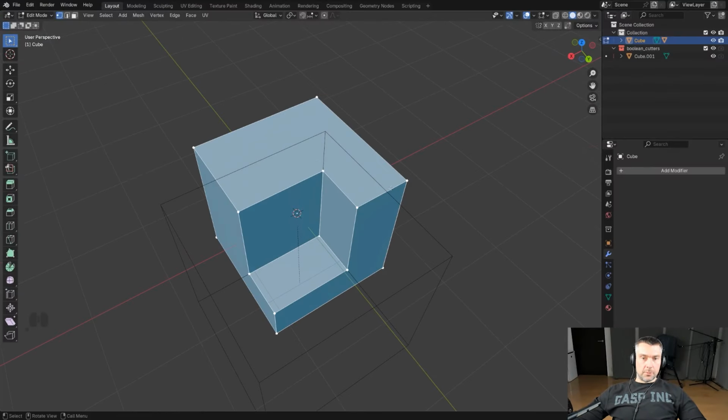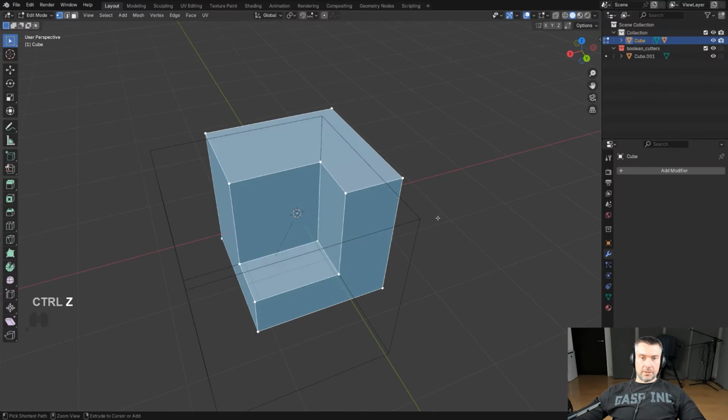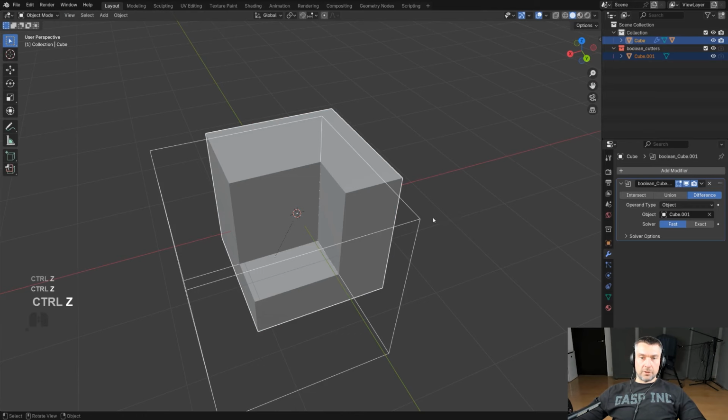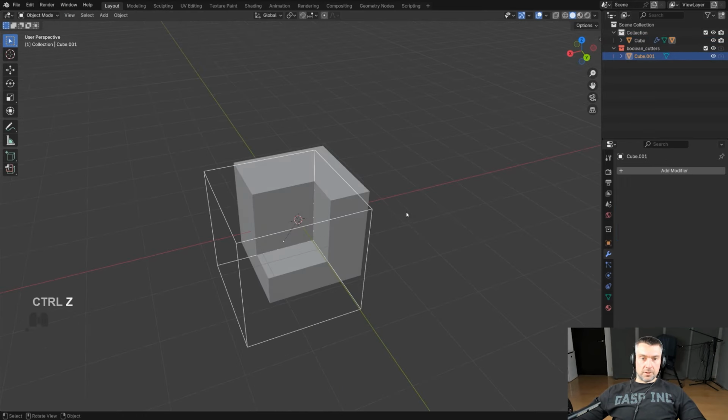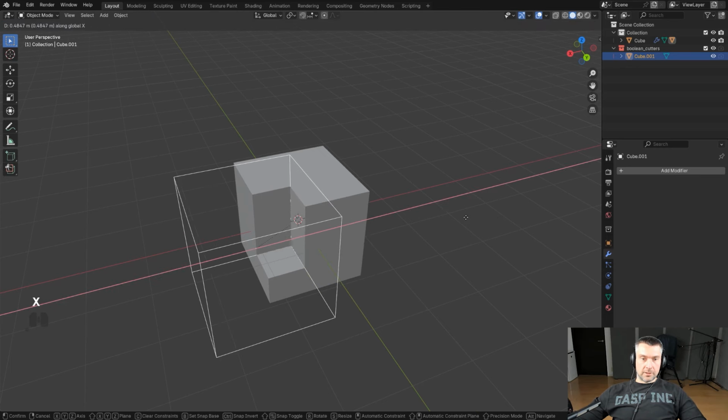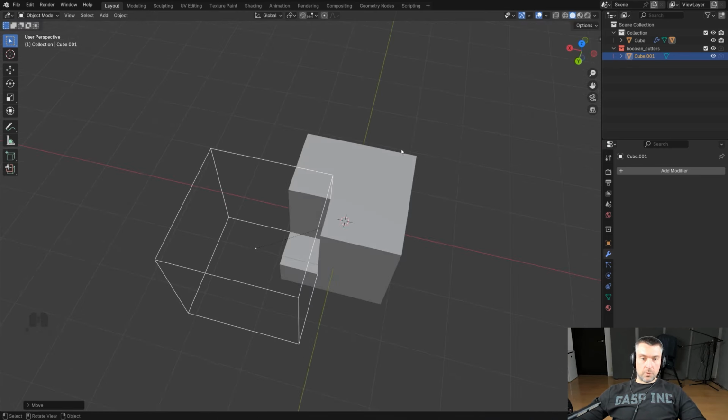All right, so going back to our problems with Blender, let's just Alt-Z this to move back in time to this boolean stage here when the boolean was actually live, and I'm going to move it with G X on the x-axis so it doesn't cross the y-axis here.